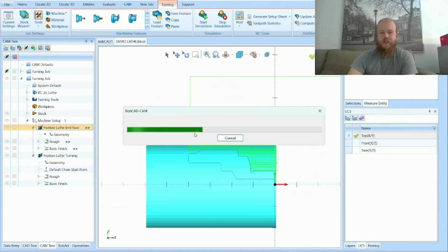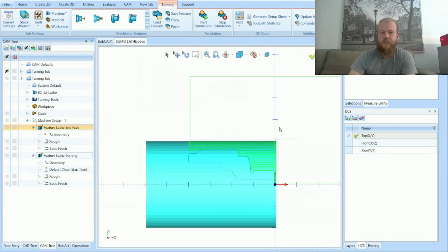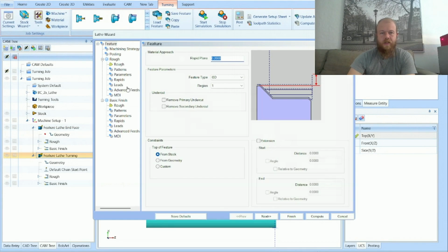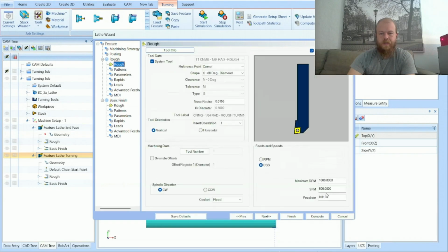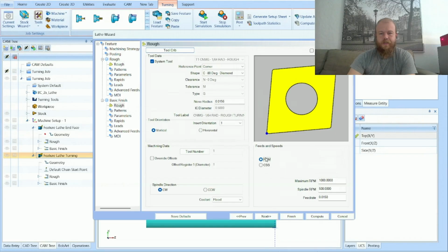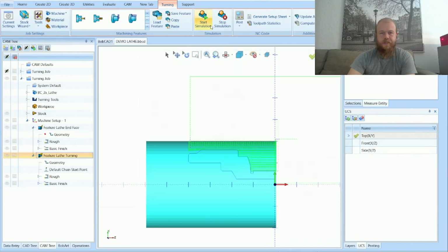And if I change just the feed rates, technically I don't have to recompute it, so I don't have to waste time computing it like this. I can just hit finish because I haven't changed any of the toolpath. So if I go to each tool page, I don't know what's going on. Maybe something in the constant surface speed. Let's take a look at the simulation now that I changed it to the basic feed rate there.